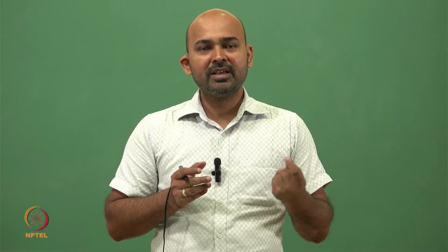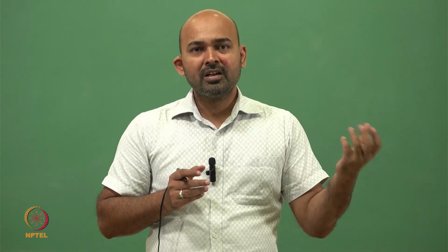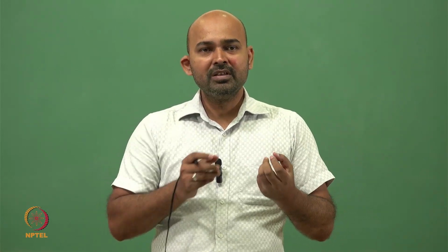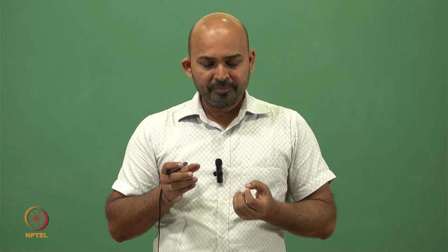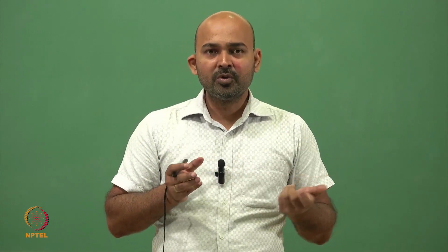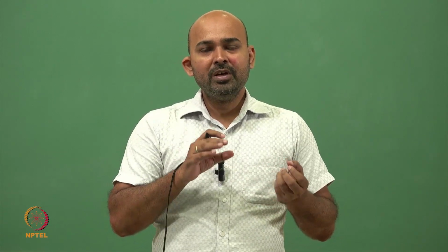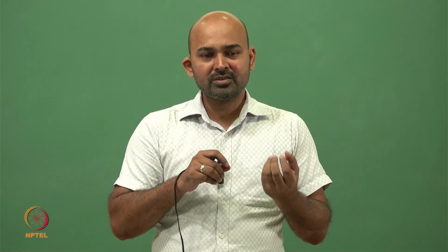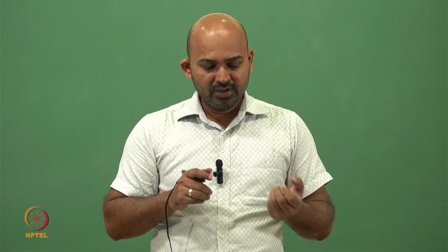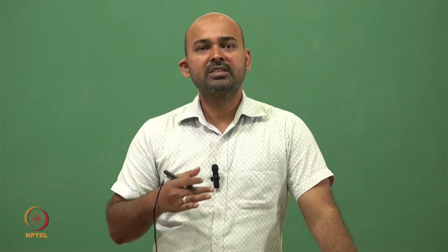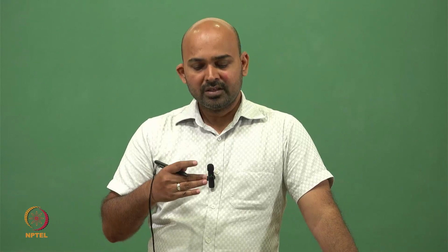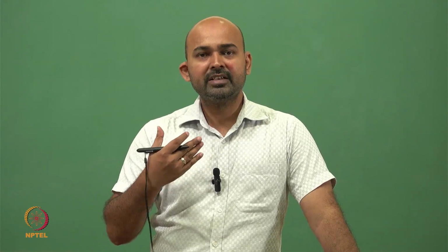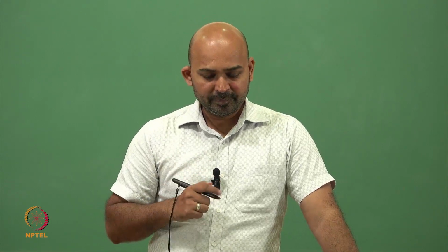If we set the pin as input, the external voltage applied to that pin will be detected by Arduino. If we set the pin as output, then the value will be written by Arduino on that pin and the external circuit is going to receive that value. So pin mode is the function to assign whether the pin will be used as an input pin or an output pin.